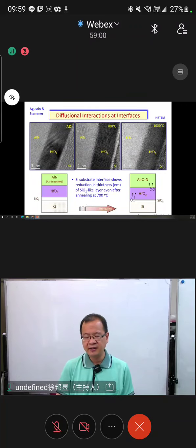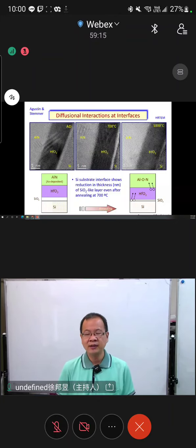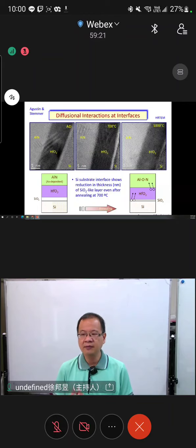And this is a very classic example in the semiconductor industry. You need to grow a high quality dielectric layer by atomic layer deposition. And hafnium oxide is a very strong dielectric that can guarantee your nano transistor survives the voltage, like 5 volt, several volt, very small voltage.